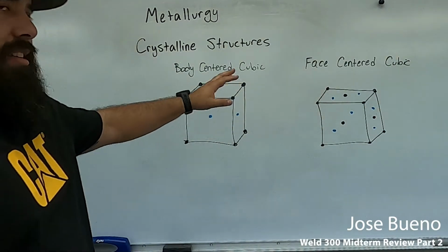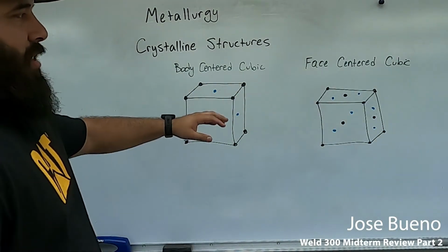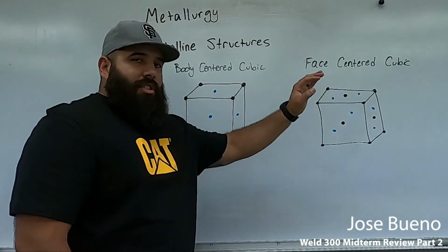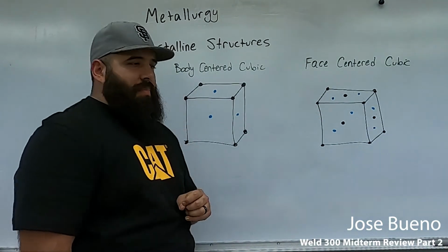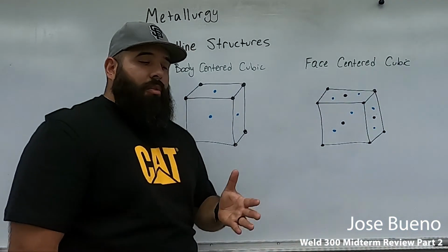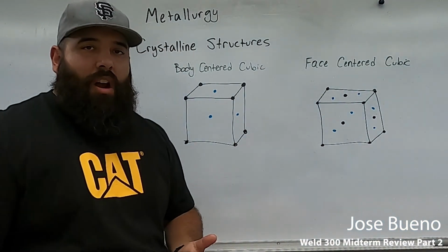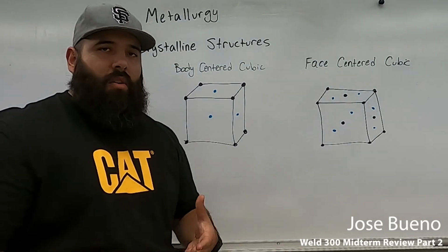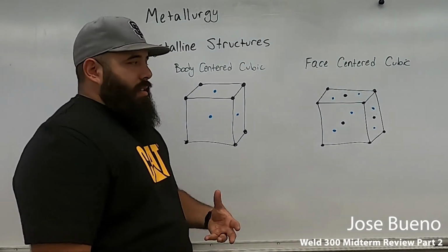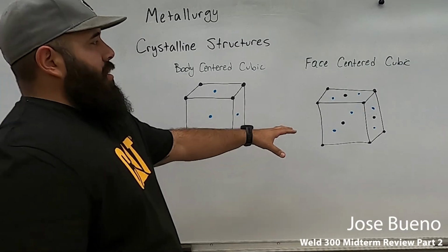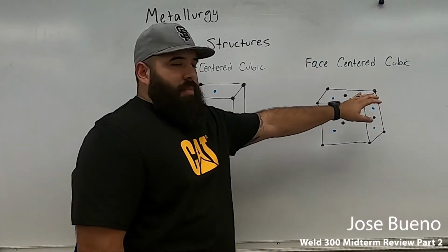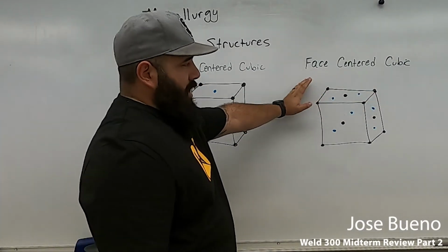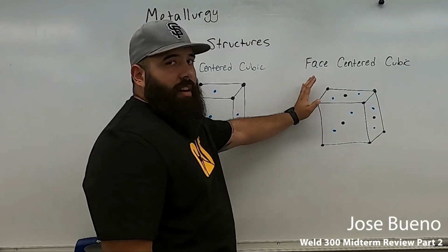Now this is as heat is applied. Once the steel reaches what's called the transformation temperature, it no longer has its magnetic properties. So think of when metal reaches an orange glow. It's no longer magnetic. So face-centered cubic: non-magnetic, transformation temperature, or just very hot.